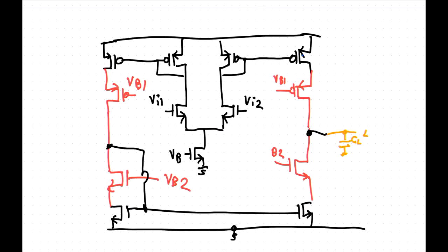Even from a power point of view, depending on how you normalize things, to get the same signal swing and bandwidth, you can get larger outputs while running at lower current, so you can actually get a power improvement. So you can reduce power consumption by making things fully differential, even if it doesn't look like it, because now you have two signal paths instead of one. You can actually do that, depending on how you normalize things. All right, so fully differential is really important.